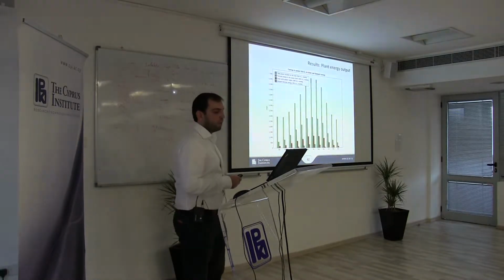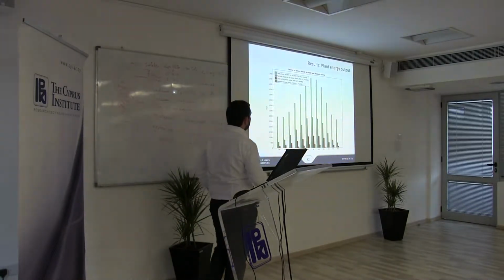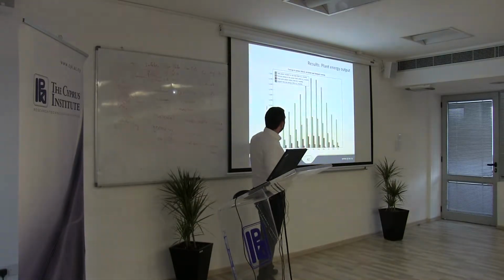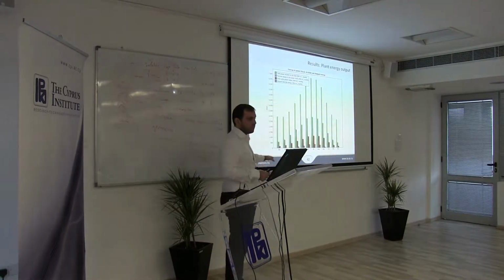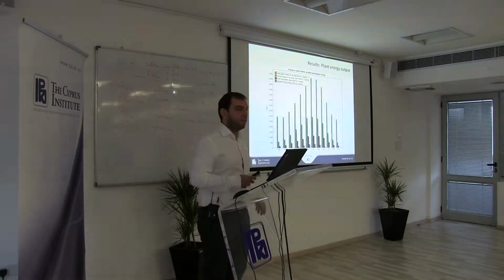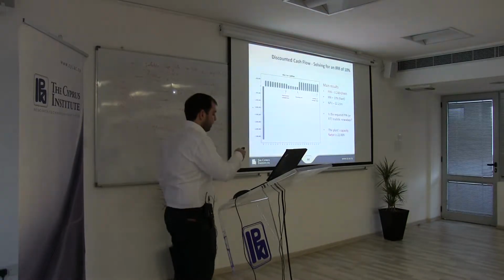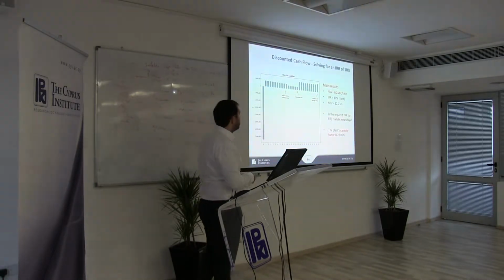Looking at the results from the plant output, we can see the total power incident on the solar field, the light green bars, the thermal energy delivered to the block, and the gross cycle power output in red. And this is basically a monthly profile of electricity generation, let's say. And by averaging that electricity generation, we can see that the plant's capacity factor is at 22.06%.